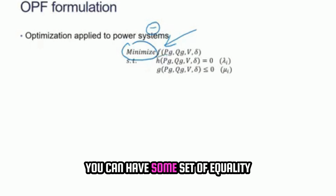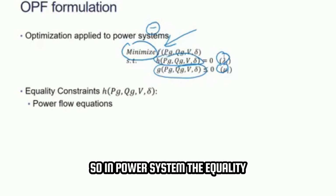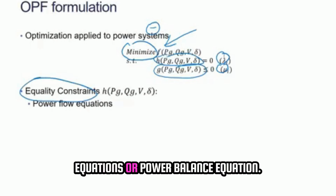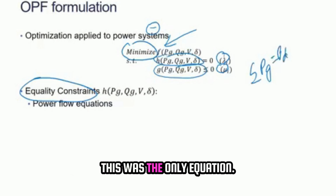You can have some set of equality equations, some set of inequality equations, and their dual variables. In power systems, the equality constraints are always power flow equations or power balance equations. In economic dispatch, the power equation was sum of PG equal to PD. This was the only equation.